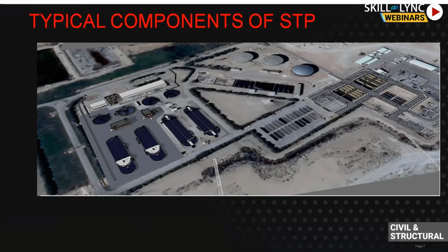Sometimes, if the sewage is too much and the ppm and pH values are not as required, we will return the sewage flow from the clarifier through a return pump station. The building between the clarifier and aeration tank, a concrete building, is called a pump station building, sometimes return sludge pump. The sludge will be returned again for another flow process. This is how a typical STP works.